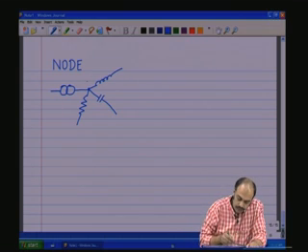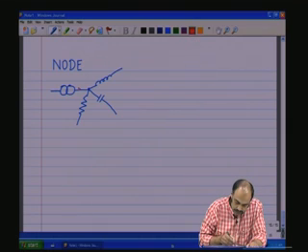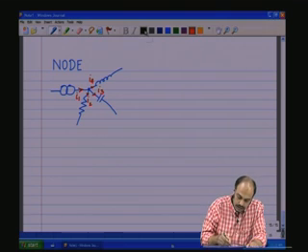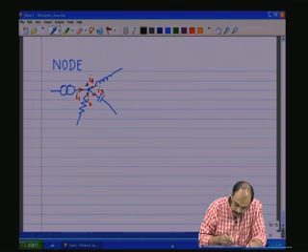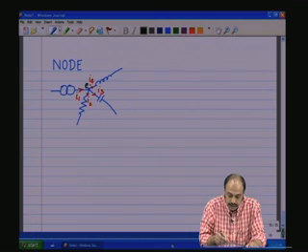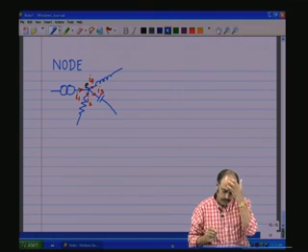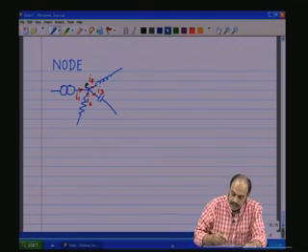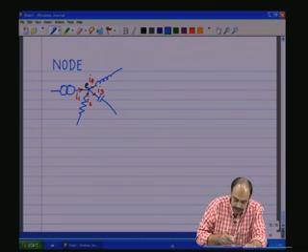Here there is a current flowing, and in each branch you will have current flowing depending upon its impedances. So, this could be, let us say, I1, I2, I3, I4, so on. One thing you should note, this node voltage is E, and this node voltage E is shared by all, the same node voltage. Again, if we apply the energy conservation principles, you will see that there should be no accumulation of charge at the node.